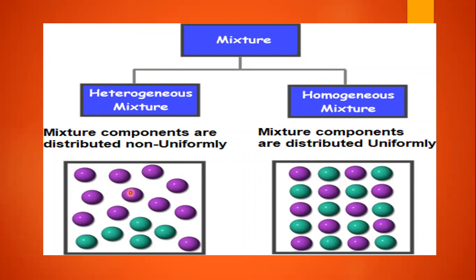And if it is a heterogeneous mixture, the equivalence ratio should be around 1 to 1.2. Why? Because here we are going to have local zones, and we maintain a high compression ratio. Here the compression ratio is around 16 to 20, but in case of SI engines it is only 6 to 10.